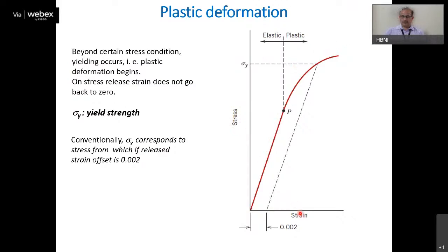If you plot the stress-strain plot, up to a certain extent it will follow linear elasticity, where the harmonic potential approximation is valid. Beyond a certain extent, it starts undergoing non-linear elasticity, where anharmonic components become active. But even in the non-linear region, if you release the stresses, the system goes back to the initial state, that is the zero strain state.